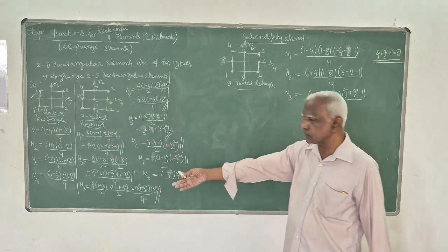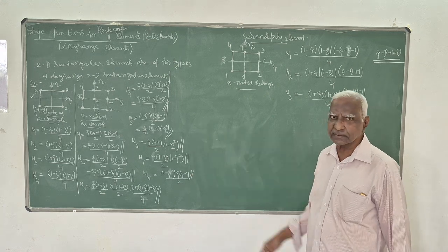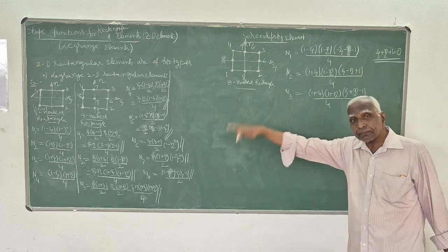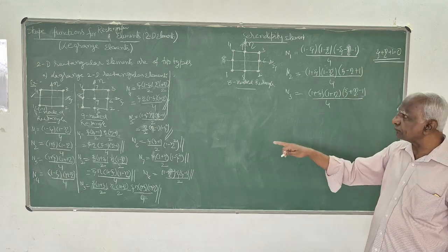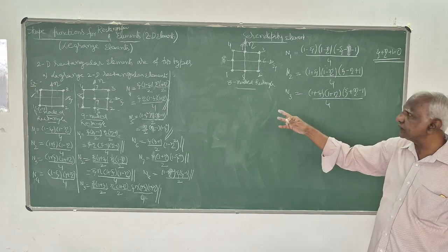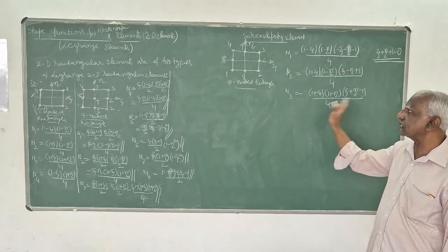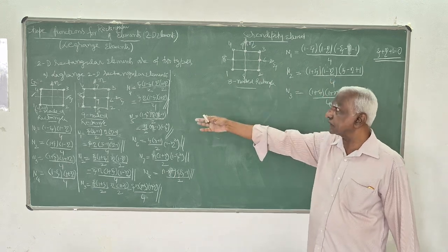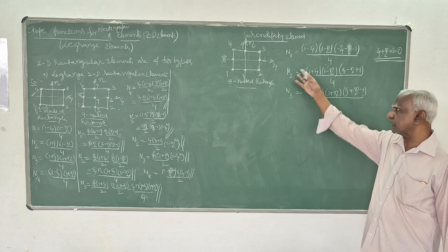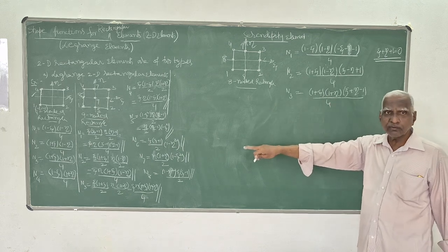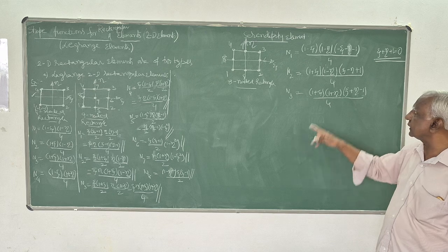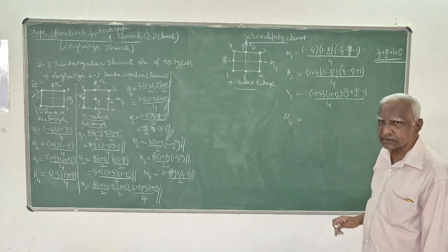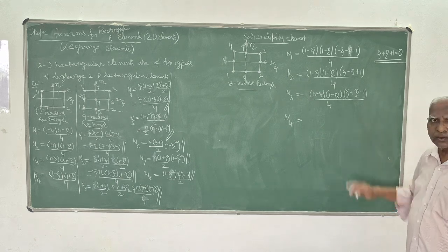You can verify all these formulas by this check. So using that property, you can write the shape functions directly. Even for the 8-noded element, though you cannot apply the Lagrange equation, you can write it satisfying all the properties of shape functions. That is one important thing.